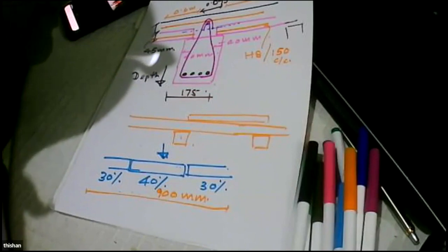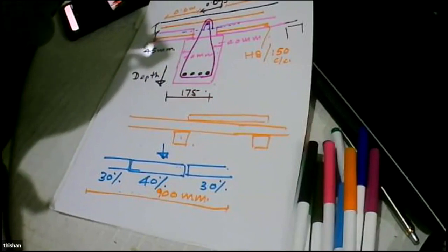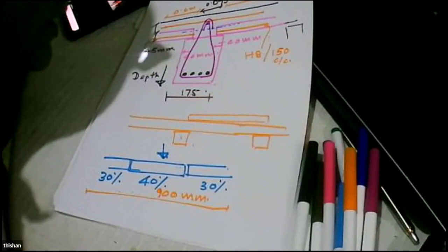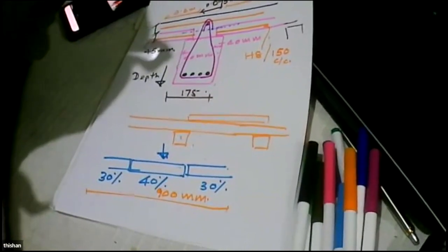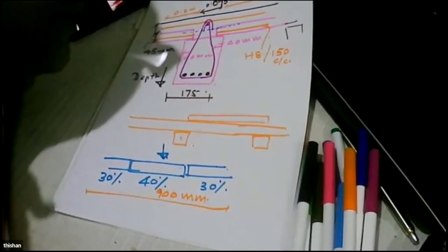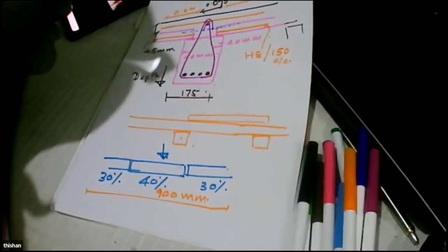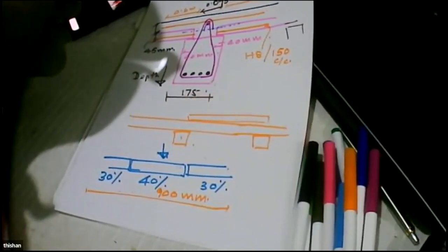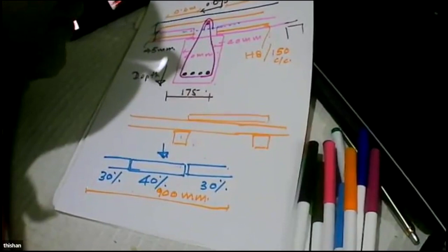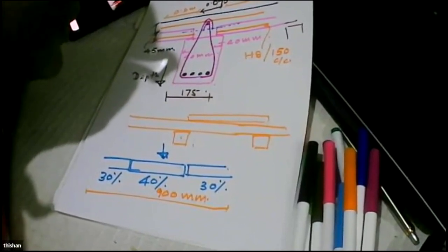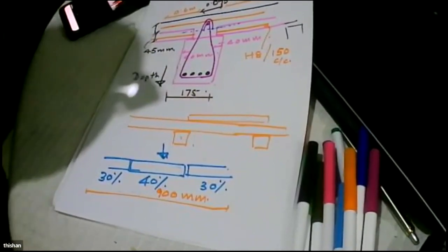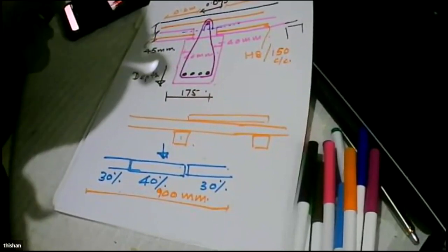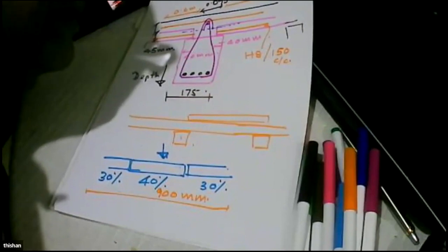Because if it is a slab, we have to evacuate the slab, right? Even if a slab has a local collapse, the whole building is not going to collapse. So what we need is about 30 minutes fire rating, and 30 minutes fire rating can be easily provided by these slabs. And if you have any issue with fire rating, then what you have to do is apply a seal. Sealing will look after that. Is that clear? Yes, sir, that is clear.